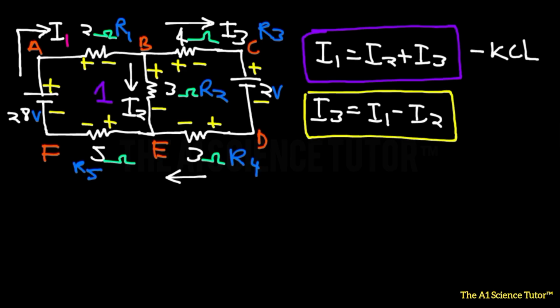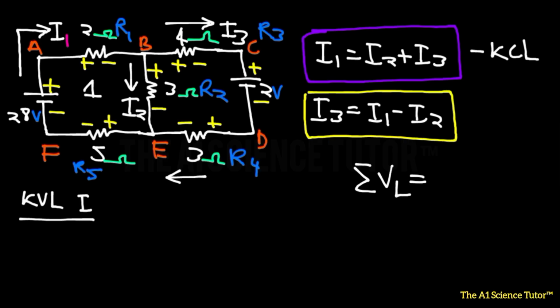So now we're going to solve this circuit starting with the first loop. So let's say this is the first loop, loop 1. And we're going to use KVL, Kirchhoff's voltage law, for the first loop. Now what does Kirchhoff's voltage law say? It says that the total voltages or potentials that will be wasted within a loop would be equal to 0. So within a closed loop, if you add all the potentials that will be wasted, that must be equal to 0.